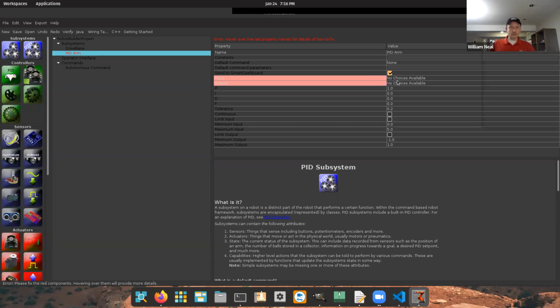There's like a rotary encoder on the arm, you might imagine. When the arm moves through different angles, the encoder counts up in proportion to the angle. And so when the encoder reaches a certain level, the robot has its arm oriented in the correct way. That's our input and output system in a PID subsystem, I suppose.